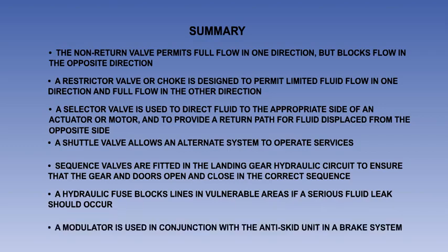And finally, a modulator is used in conjunction with the anti-skid unit in a brake system. It allows full flow to the brake units on initial brake application, and thereafter a restricted flow as controlled by the anti-skid unit.